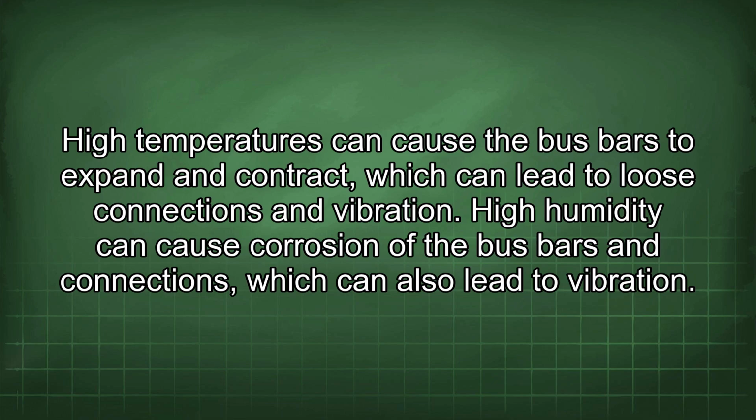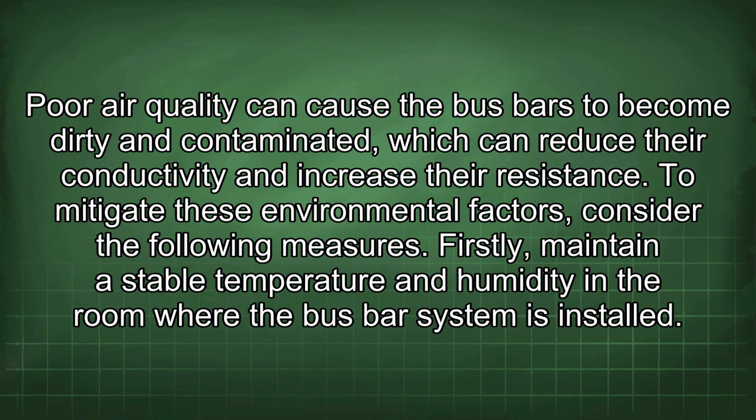High temperatures can cause the busbars to expand and contract, which can lead to loose connections and vibration. High humidity can cause corrosion of the busbars and connections, which can also lead to vibration. Poor air quality can cause the busbars to become dirty and contaminated, which can reduce their conductivity and increase their resistance. To mitigate these environmental factors, consider the following measures.